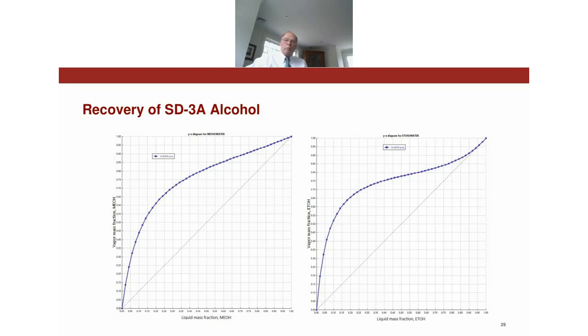And, you know, the equilibrium pinches, and at atmospheric pressure there's actually an azeotrope between ethanol and water. So most of the stages are up in this region of this diagram. And so in reality, most of the stages for this system were above the feed.